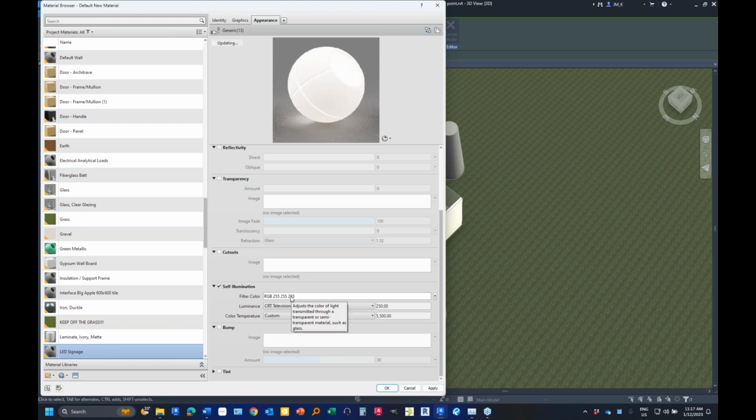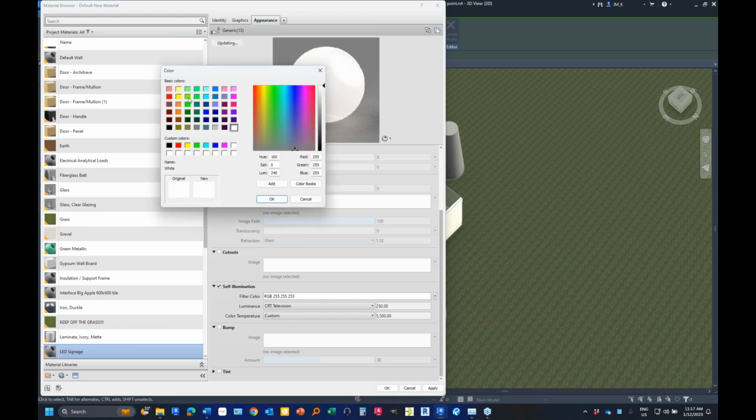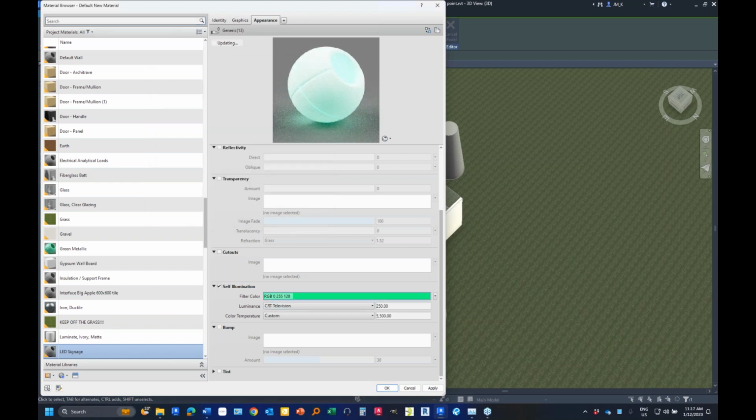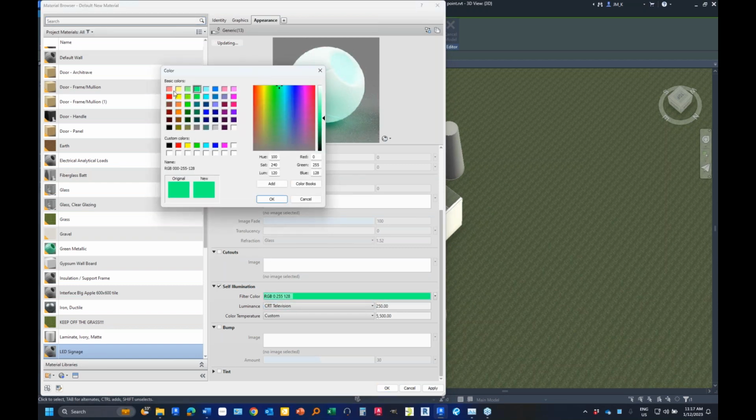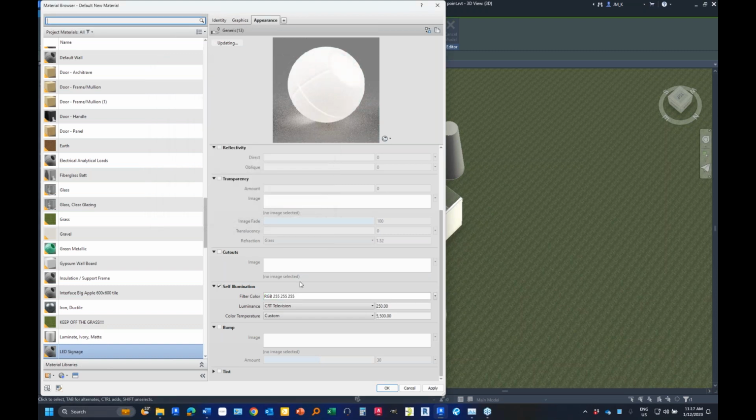So I've added in a color filter. Well, actually, the color filter just stayed the same. If I add in a color filter, you can see it's a bit like adding a piece of colored acrylic on top of a light source. But in this case, it's white acrylic. It's, let's say, going to have a lampshade sort of lightness, or maybe let's make it a bit bigger. 2500 lumens. Color temperature, I've made it slightly warm white.